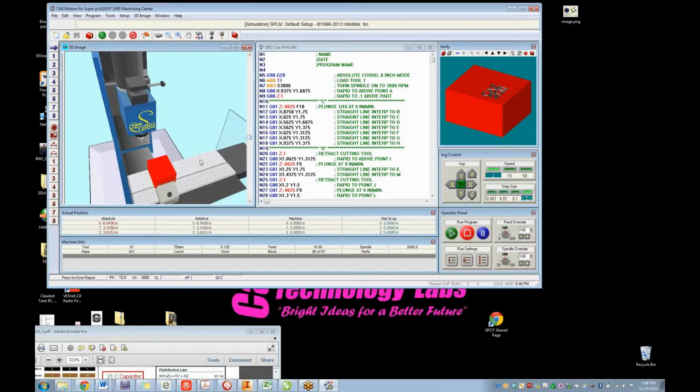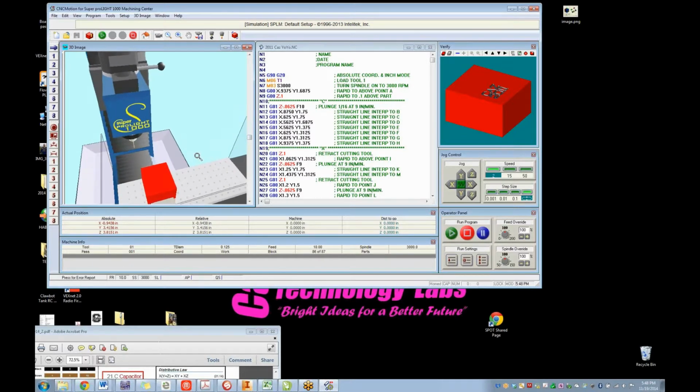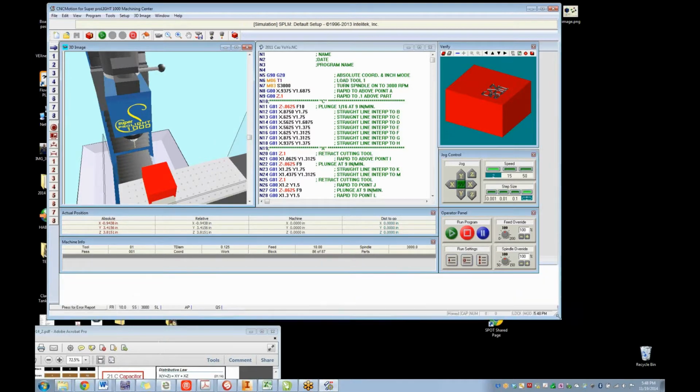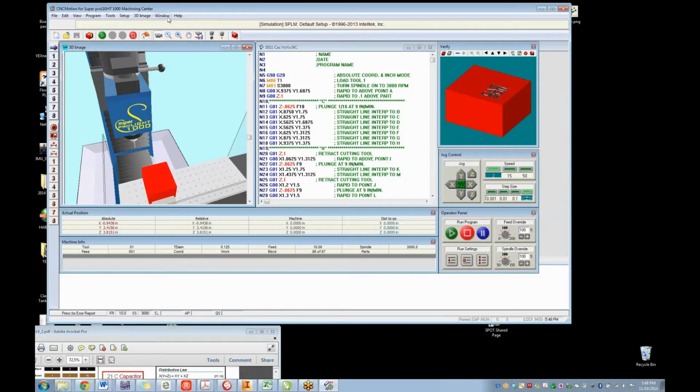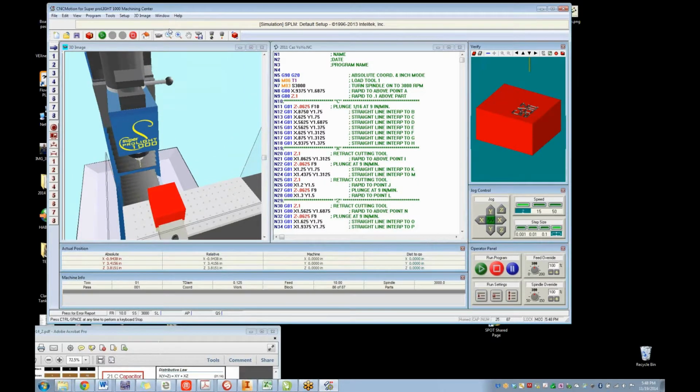When we're writing arcs, I told you a minute ago, I don't have my kids write incremental arcs. In the real world, EdgeCam, MasterCam, SurfCam, all of them, they will do incremental arcs. Every arc they do is incremental. I don't know why, but they do. You'll have to teach the software to interpret all the arcs as incremental. When they handwrite them, they have to interpret as absolute. So they'll get it and they'll write the whole thing up.